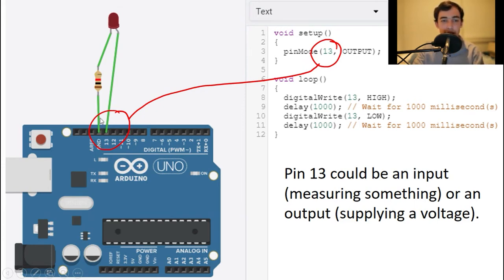This one side of the circuit, this is basically a full circuit. So the wire connects to the resistor, that connects to the LED, that connects back down here. And in between these 2 points, it's actually connected in the Arduino if we code it right.